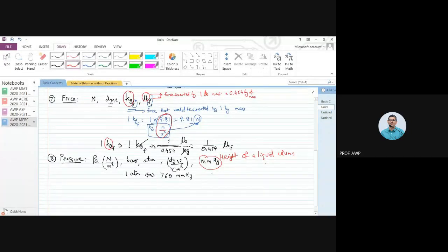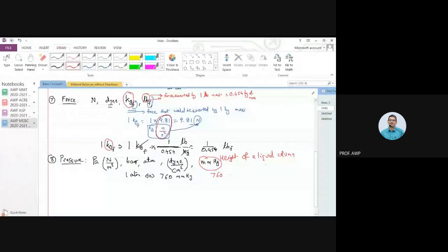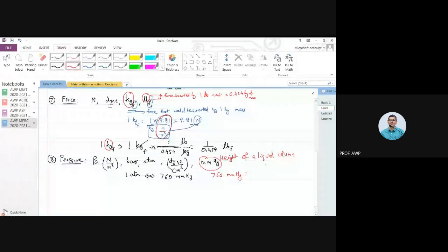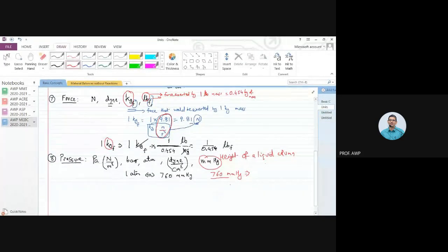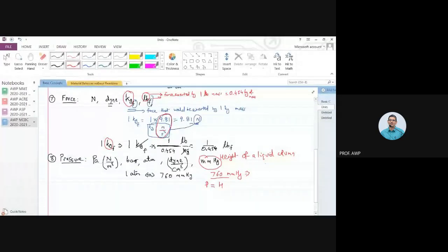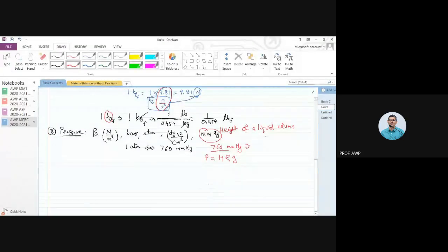So if I say 760 millimeters of mercury, the height is, what is this number telling us, 760, and the pressure that is arising out of this much amount of height, we can calculate in terms of h, the height, into rho, the density of the liquid, and g, as the static or hydrostatic head or hydrostatic pressure that corresponds to this height.